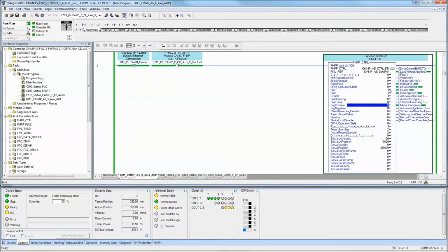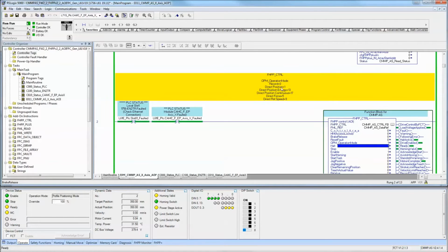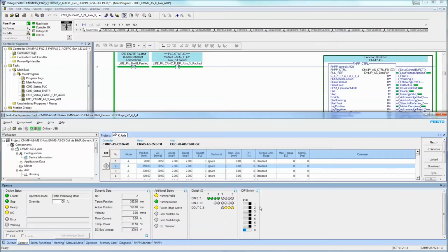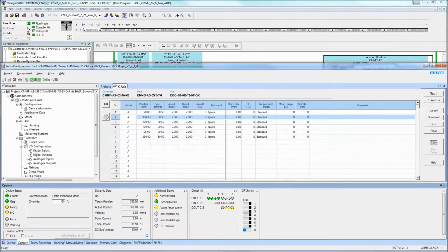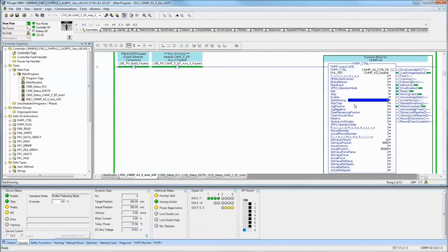So next thing, we'll just show a quick little sample. We're going to go into record mode. Record mode or direct mode is 1. And in this case here, you will put a velocity and a value. So when we talk about that, we're talking about the direct mode. So the base velocity is 1,000 millimeters per second. If you look at the memory map, this right here is a percentage of that value.